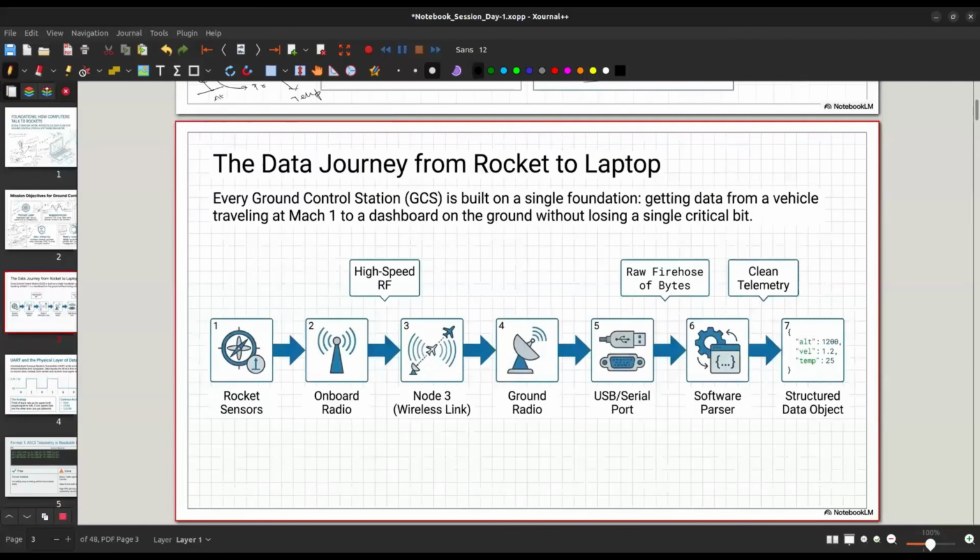What is corrupted packets? Corrupted packets in the lecture, in the sheet probably. Yeah, the corrupted packets is basically you're trying to receive certain data packets from the rocket to the GCS, but there has been some kind of a problem due to transmission loss or data loss. So you were supposed to receive 72 packets at a time, but you are only receiving 71, 70, sometimes 60. Worst case, we haven't received a packet for at least 3 seconds, and that was basically due to the synchronization problem.